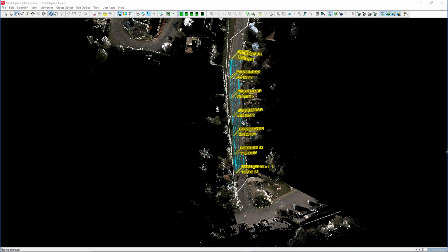And we can close our software and zoom all. And put points in. Okay, now I use these ones here. I did them a little bit earlier, but I now have all this data. And of course, I can export this as AutoCAD data. I can export this as a CSV file as points. And once again, be able to then bring this data in to Civil 3D. Okay, and of course, create a surface out of that type of data.